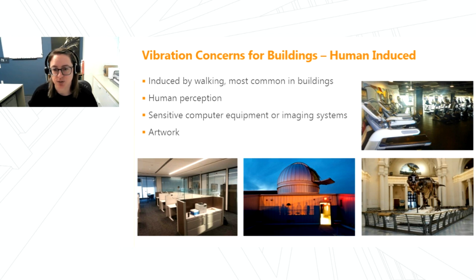Often solutions include special raised floor systems to help limit the vibrations and special hangers for ceiling fixtures below. Human perception can also occur due to just someone walking around next to you on the floor. If flexible monitors are not locked into position, as the floor vibrates, the vibrations can easily translate to the monitors. Sometimes just swapping out the monitor arms can reduce the human perception to an acceptable level.